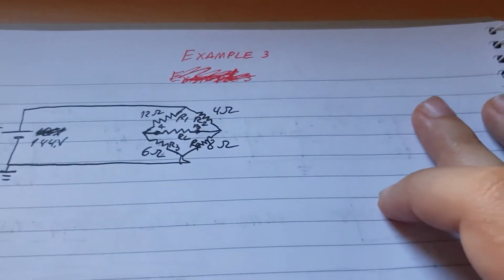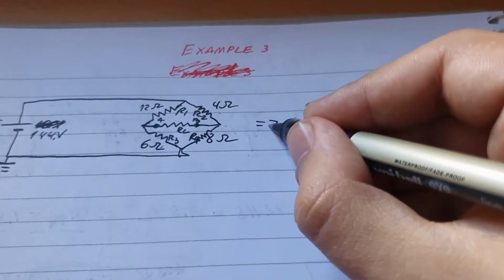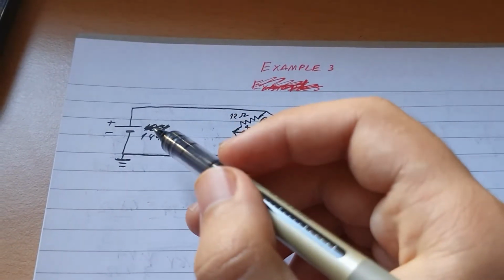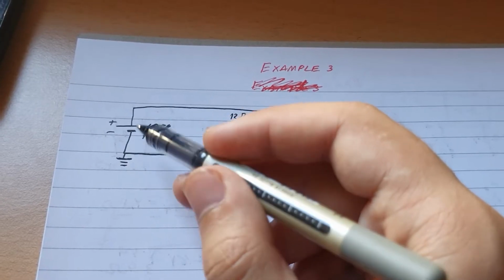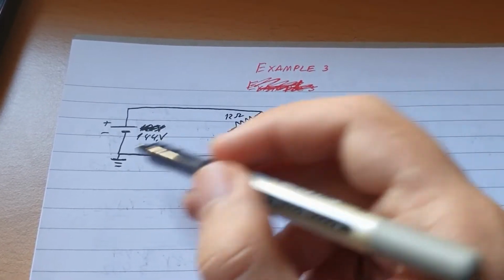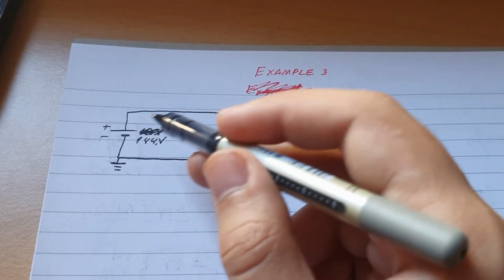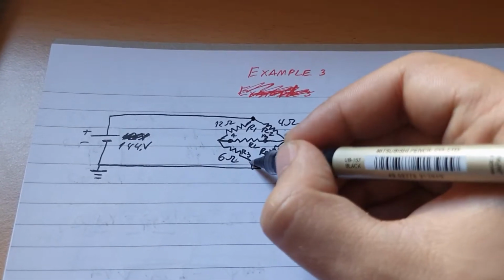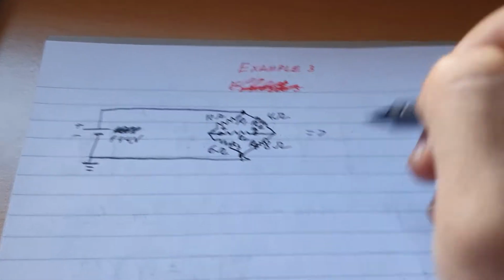Now let's go for the second step, which is finding it out. This voltage source will become a short circuit. So then there's nothing going through it, it's just an open circuit. Therefore, we are going to use only this section here. So we can redraw this as follows.